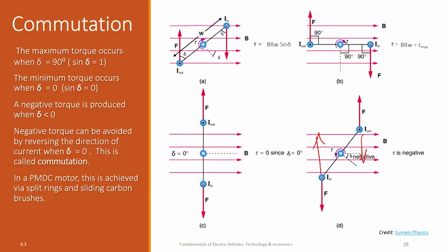But this is the way it is done, and even if I found a cleverer way of avoiding all this mechanical contactor and jumping, it will not work here, because then the wires will simply come out and start twisting against each other and snap. So, just to isolate the wire leads going to the plug from the rotating armature, I need to have this arrangement to separate them. So, this is the overview of what is called commutation and why we need to flip the current.